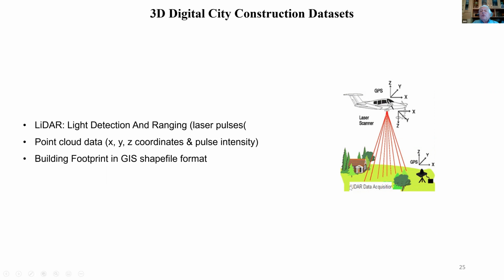We are not going to rebuild anything practically. For those who may not know, what we use for that is called LiDAR data. Essentially, look at this plane. It sends laser pulses, and these laser pulses hit surfaces or buildings or trees, and then they bounce back. Using the time of bouncing back, which goes very, very quickly, it is possible to measure the height of the point that was hit by the laser pulse. That is a very, very useful piece of information. It is available publicly. The city of Columbus has conducted a lot of data gathering, though they are not using it very much, but it is available, and we've used it also for the last piece of research.